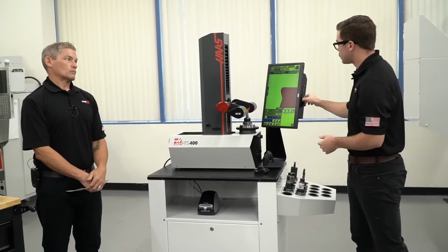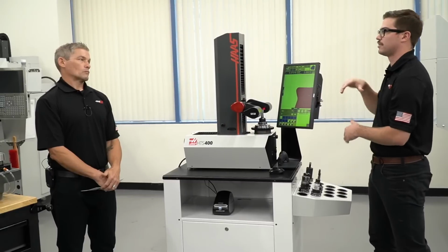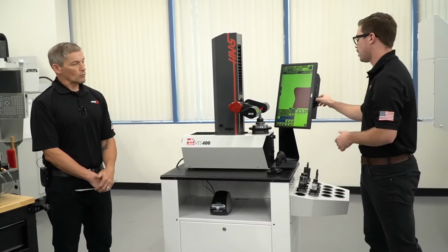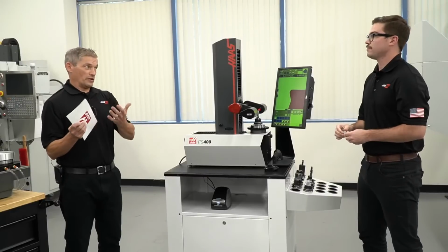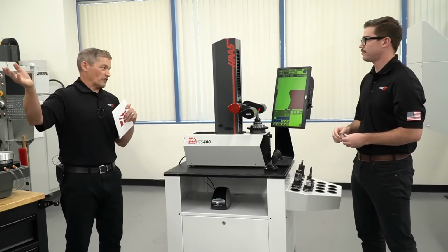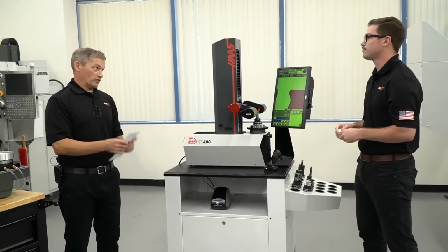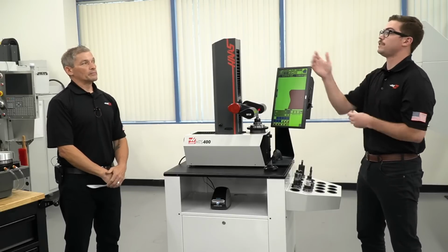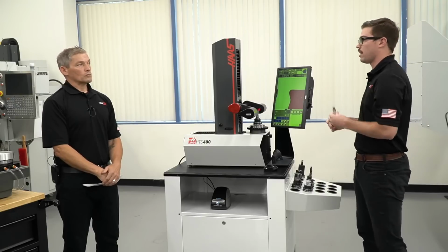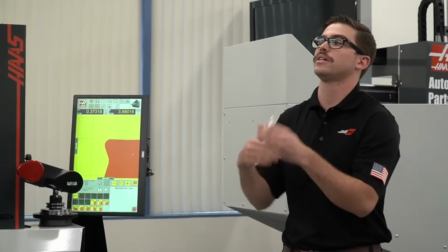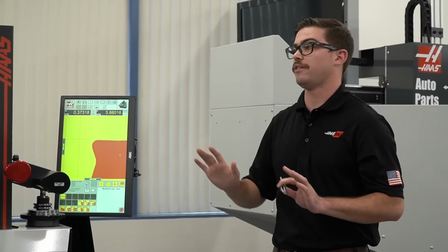Another thing you can do is take those offsets, because we created an entire tool list. You can then export those as an offset file onto a USB. And then you can go over into your control, plug it in, upload that offset file, and then it'll automatically update your tool geometries. Right, so you might load a whole new job, 10 tools or something, and you're going to update all of that at once. Correct. And even if you have 50 tools and I only want to update the geometry on 3 of those, I still create this one offset file. When I load it into the control, it's only going to update those 3 tools and leave the remaining 47 tools totally fine.